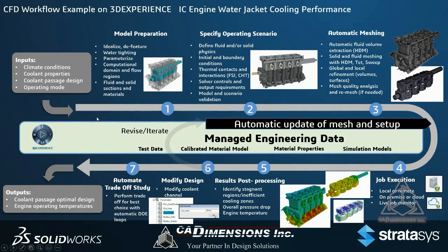The model preparation, obviously we need to idealize our geometry, defeature anything that's not super important, like cosmetic fillets, extruded text, things that are going to be difficult to mesh or that are going to jack up our mesh count way more than we need it to be. We're going to go ahead and specify our computational domain and our fluid flow regions.